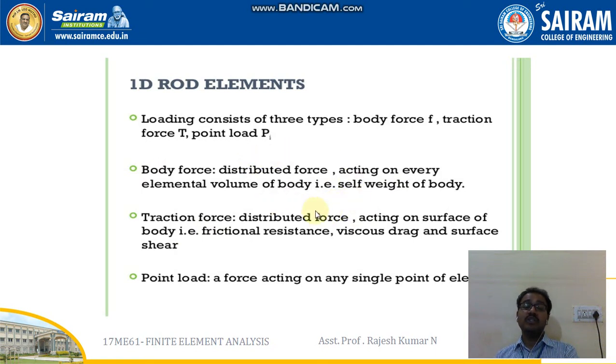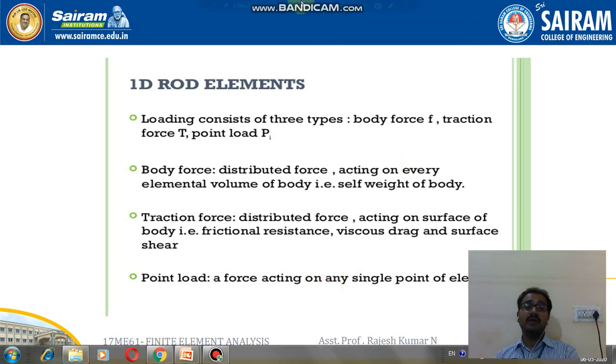So the condition is, if you are applying a body force or a traction force, before itself, at that particular boundary or location, as much as possible try to establish the nodes, because the forces can be applied only on the nodes. But in case of the point load, that is not the case. After the discretization and after defining the geometry, a point load can be applied at one point or another. So like this only it can be converted.